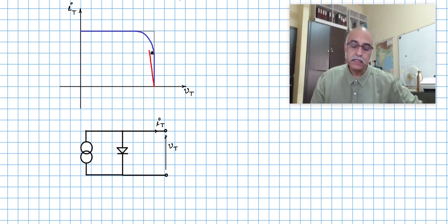This represents a series resistance drop. So as the current increases, you will see that the drop from the constant voltage line keeps increasing. This is the IR drop. So if you say that the series resistance is RS, then this slope here would represent the series resistance in the model.